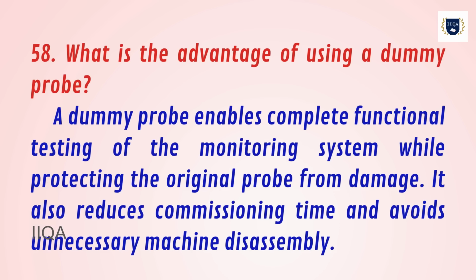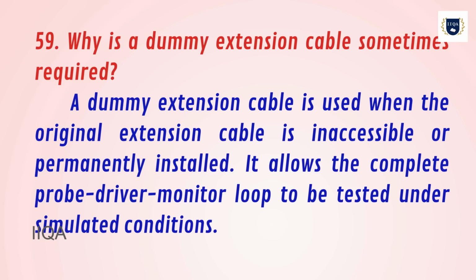58. What is the advantage of using a dummy probe? A dummy probe enables complete functional testing of the monitoring system while protecting the original probe from damage. It also reduces commissioning time and avoids unnecessary machine disassembly.